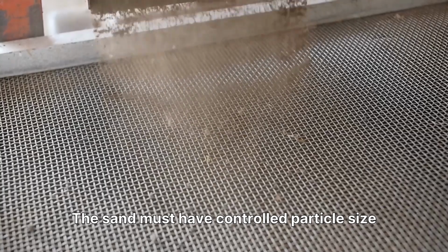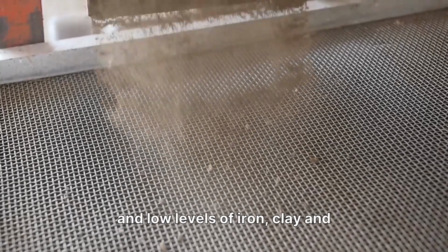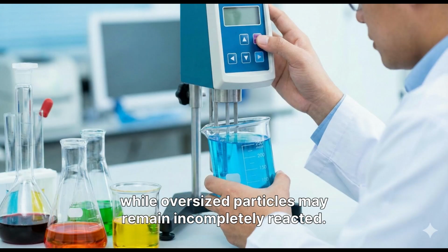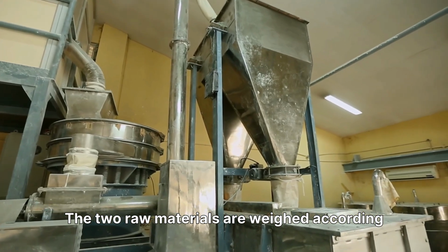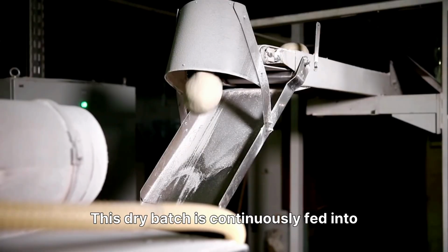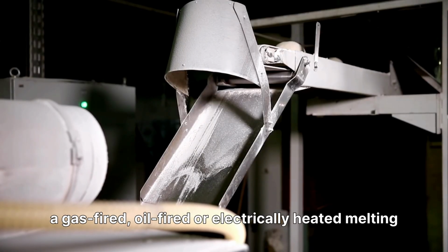Production begins with high-purity silica sand, principally silicon dioxide, and dense soda ash, chemically known as sodium carbonate. The sand must have controlled particle size and low levels of iron, clay, and other contaminants. Excess iron can discolor the final product, while oversized particles may remain incompletely reacted. The two raw materials are weighed according to the required silica-to-soda ratio and mixed thoroughly.